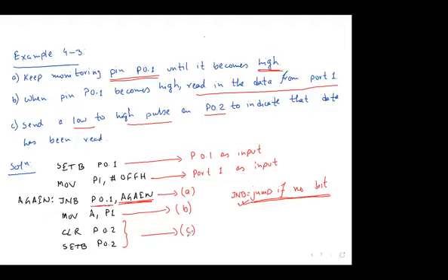That is not included in the content right now. So just know that the initial value that you set only tells the microcontroller whether it will act as input or as output. Then when you go for checking the bits, this value that you have set initially does not affect it. It totally depends on what you are getting from the device. Did you understand the difference? I got your question actually. Yes, did you understand the difference?